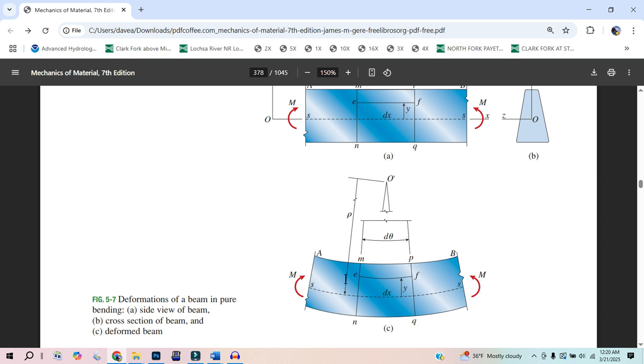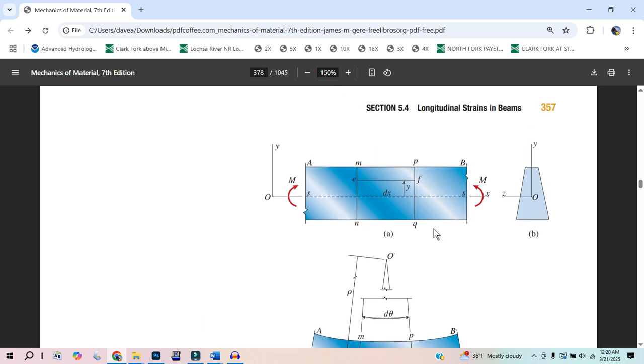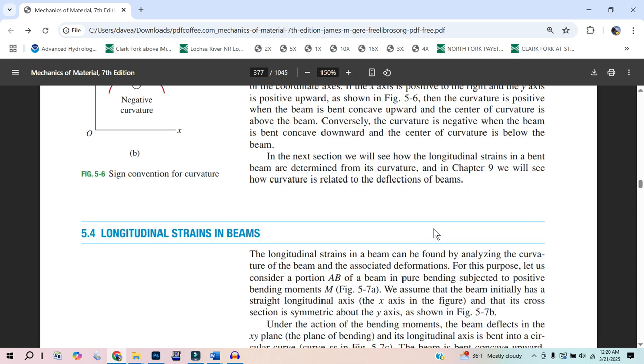And then the other thing to visualize is, have this welded vertical. And you can even see from this picture, we curve up quite a bit. But if we go back to the shear forces, those shear forces just don't cause much deformation. The angle that you will see in the downward direction is negligible. And I haven't run the numbers. Chapter 9 just says it's negligible. I don't know if it doesn't even change 3 decimals, or if it changes the second decimal, or if it's 1%, or a 0.5% change if you take into account some of the shear forces changing.